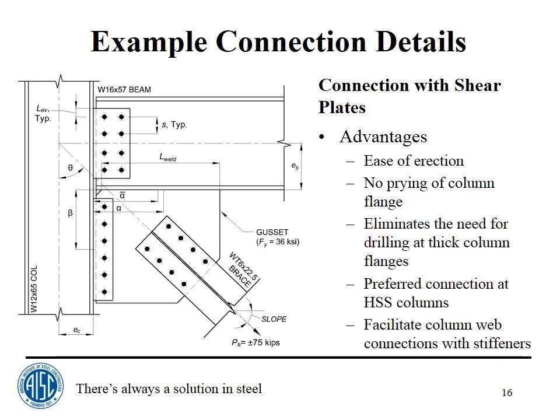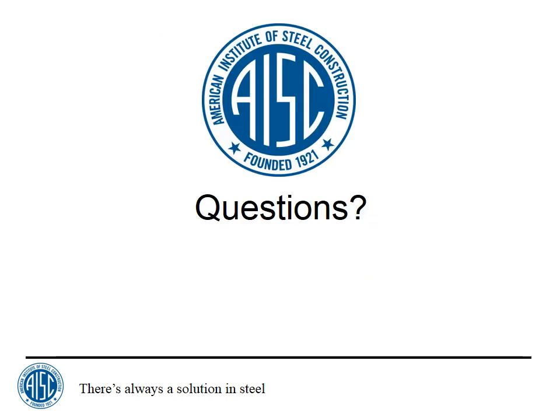Correct. I would say that in our procedure for that, in my way of looking at this, only the inside two columns take the axial force. All four columns of bolts will share the shear, but only the two columns of bolts that are closest to the beam web and the gusset take any of the axial force. The other two take nothing. There's no way that you can argue that the axial force can get to those two outer columns of bolts unless you use stiffeners. And certainly we do not want to do that because it's very expensive.